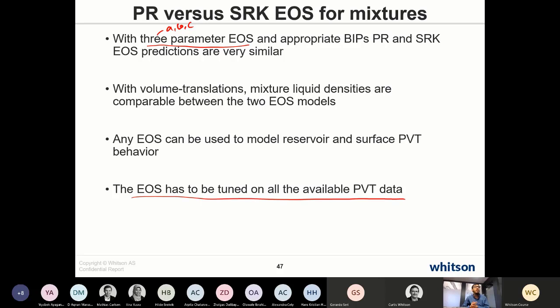So you should have some vapor-liquid equilibrium data, for example CCE tests done at low temperatures, or some other measured data at low temperatures, to match your equation of state model to, to be more confident that the cubic EOS will give reasonable predictions at those temperatures when you start using it for wax modeling, for example. Thank you.